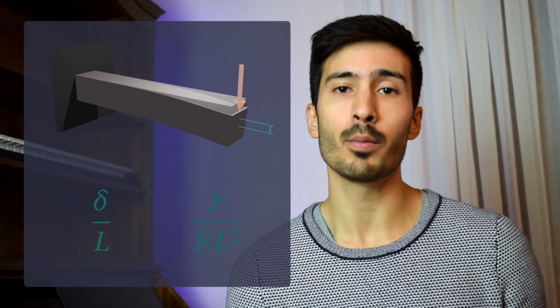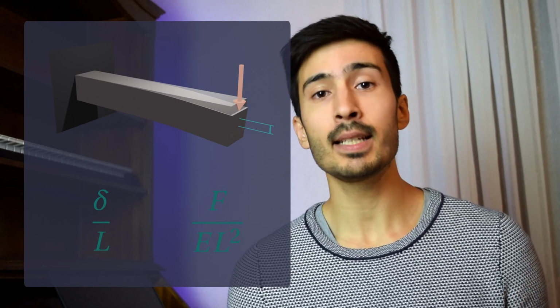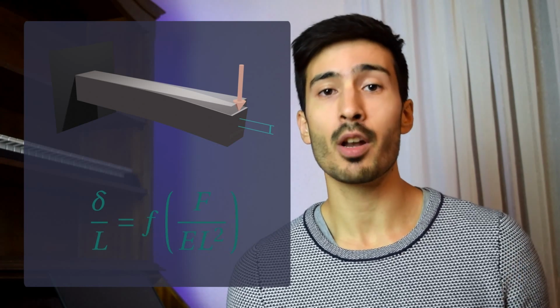But the Young modulus of a material is a measure of its stiffness. As with a common spring, the stiffer the material, the smaller the deflection will be for the same applied force. By inspection, we can easily find these two-dimensional groups. Using the same argument as before, we can write an explicit expression for the deflection of the beam.